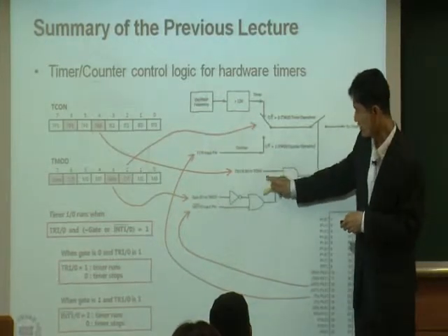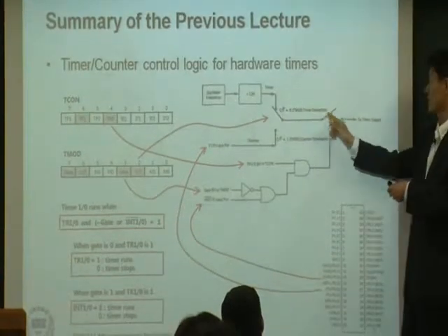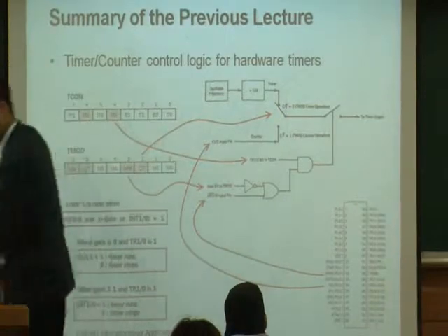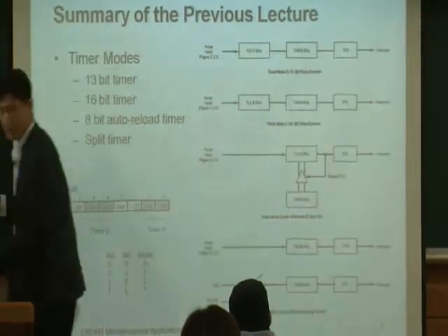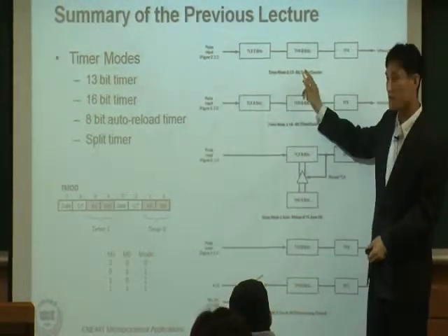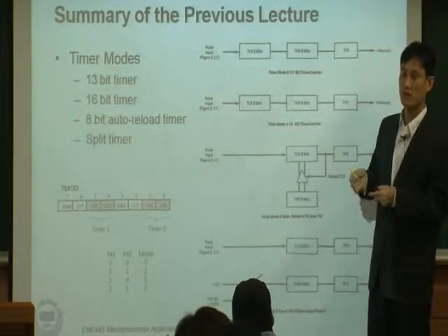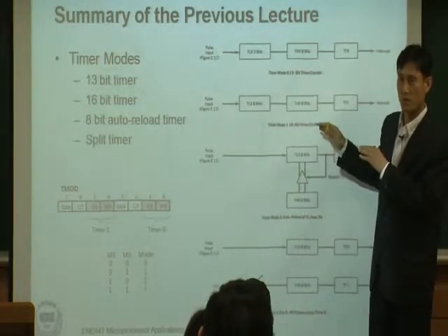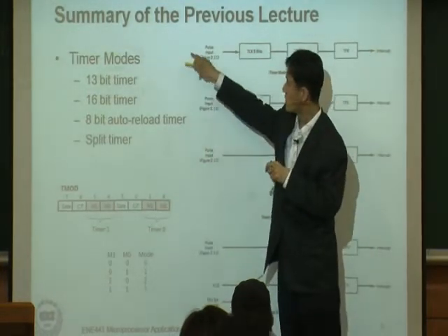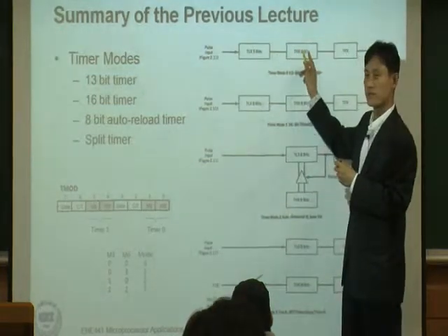So when you set it to 1, now this switch is closed. Your pulse train is now coming to the timer hardware. Therefore, that pulse train eventually comes into the timer. Which timer you use, you have to program it before, right? You already have a program for which timer you use. Okay? So now when you run it, your pulse train comes in here, and this is simply a counter.